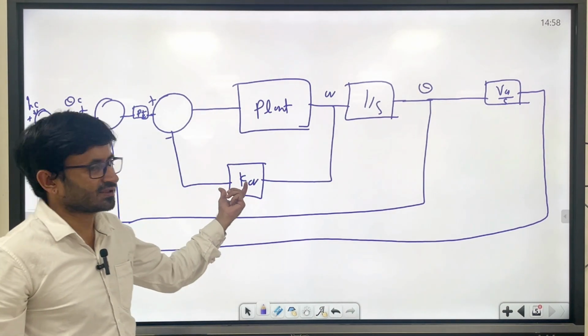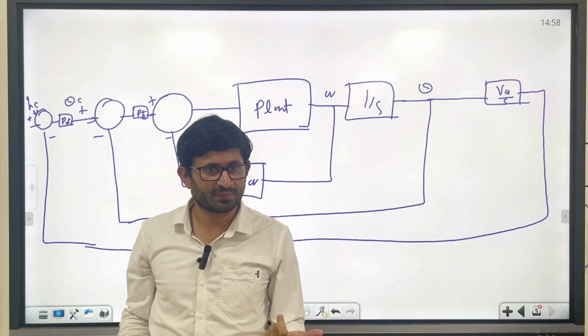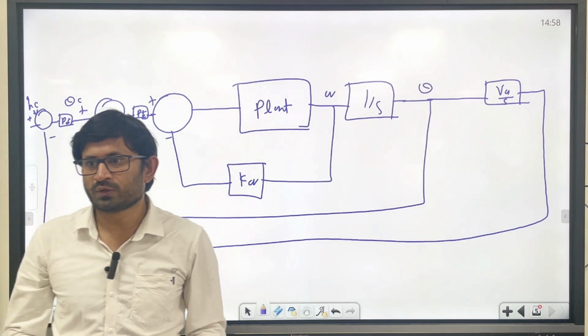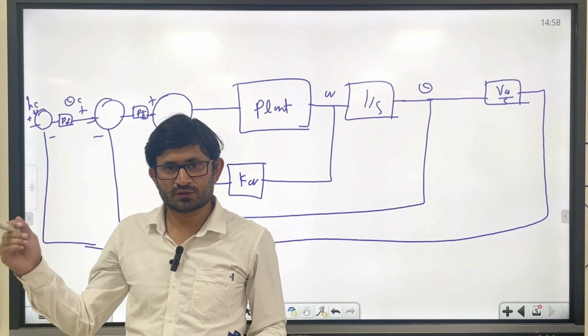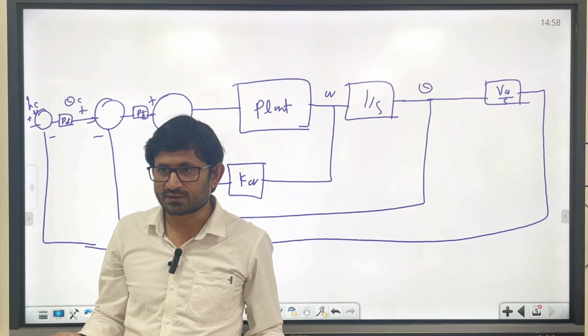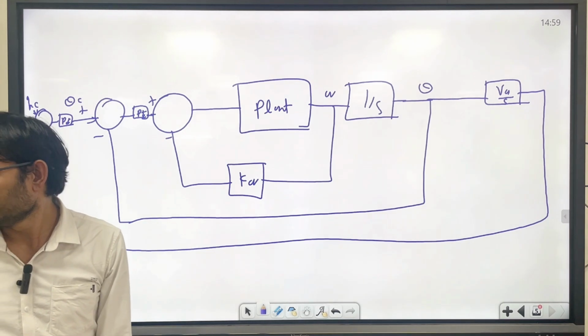This gain is obtained based on root locus in order to ensure proper damping. Then in the next loop, you tune the PI to get a good response, with overshoot less than 10% and settling time 5 seconds. If the requirement is satisfied, you move to the altitude loop.